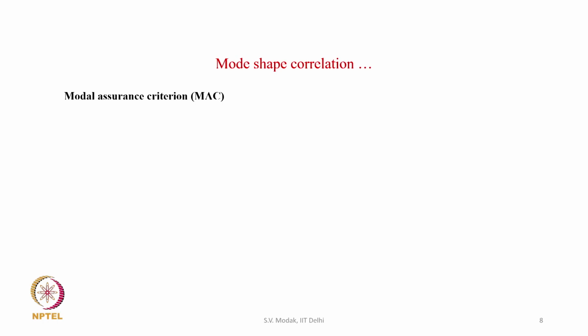So, how can mode shape be used for pairing of the modes? One approach which can be followed is based on visual comparison. For example, we can plot the mode shapes from the FE model and the mode shapes identified from the experiment, and then compare them visually to see which modes present the same mode of vibration. Based on the distribution of the nodes and antinodes, we can determine which two modes correspond to each other or represent the same mode of vibration.